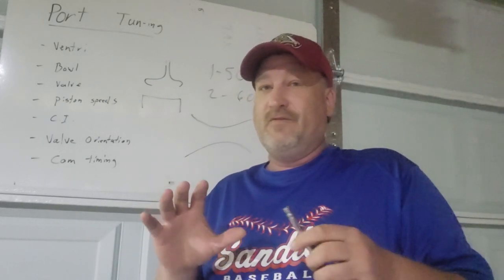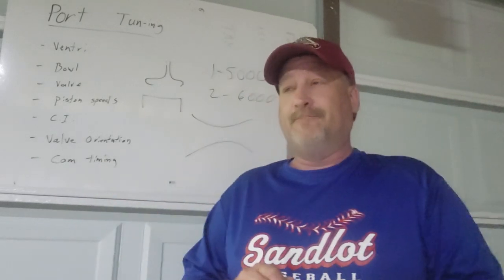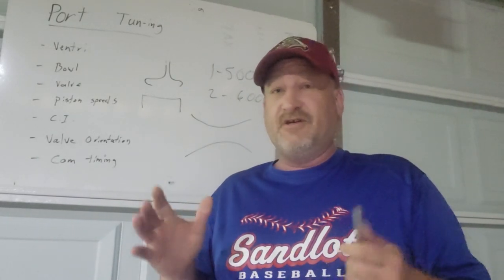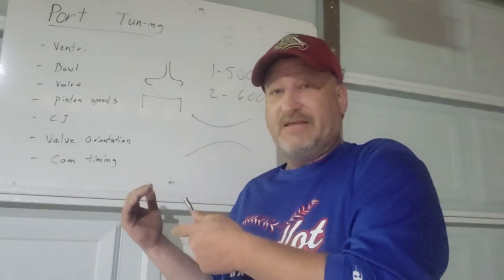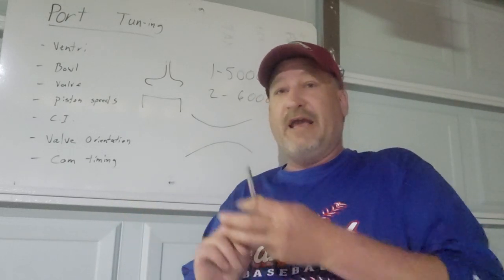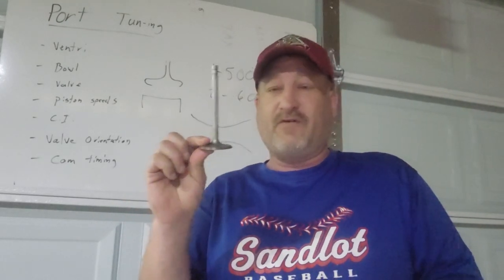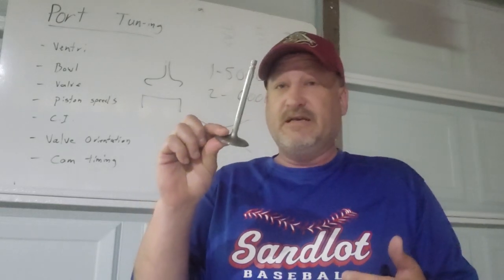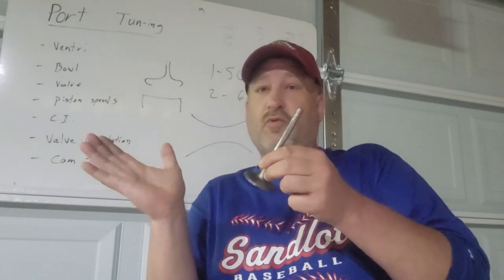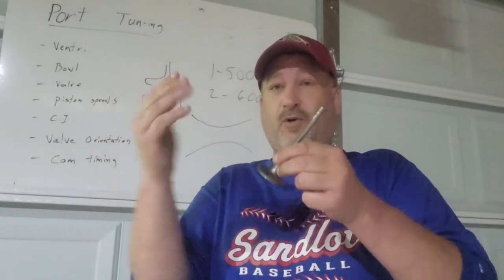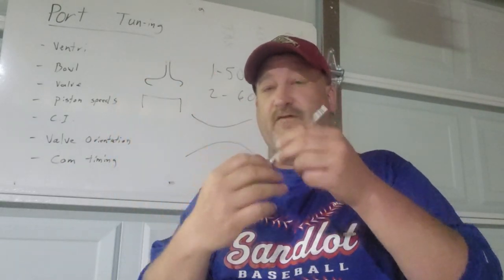So typically the best orientation of valve angle is contributed to by the actual height of the intake port itself. So as the valve is canted from, say, 23 degrees to 18 to maybe even 15, there's a relation between the height of the port and the approach to the back of the valve.